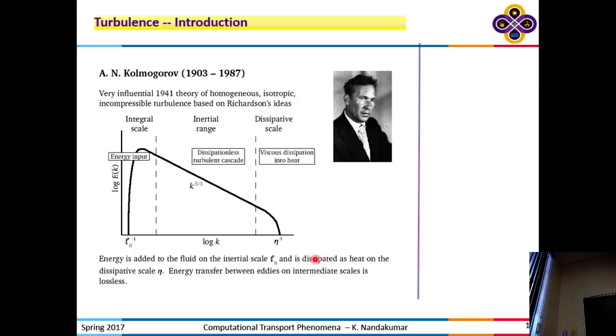So this is called the Kolmogorov scale, the length scale of the eddies at which the energy is irreversibly converted into heat. And this is the equipment scale, the integral length scale, where you put in energy through pumps, through stirrers, etc. What he did was simply use dimensional analysis. At that time, in the 1940s, we couldn't solve the Navier-Stokes equation. We didn't have powerful computers.